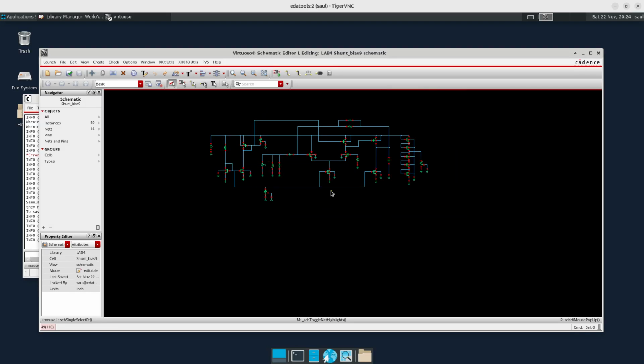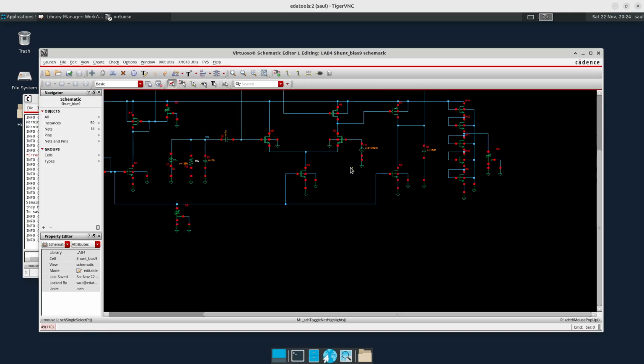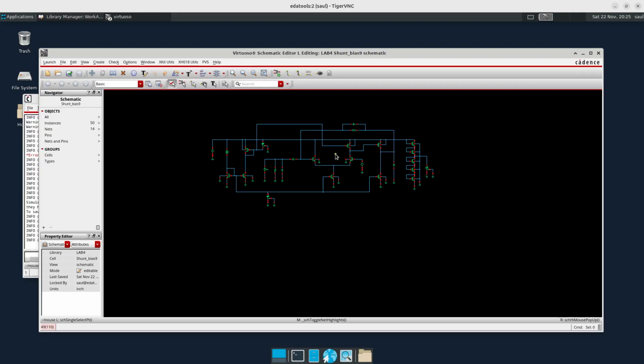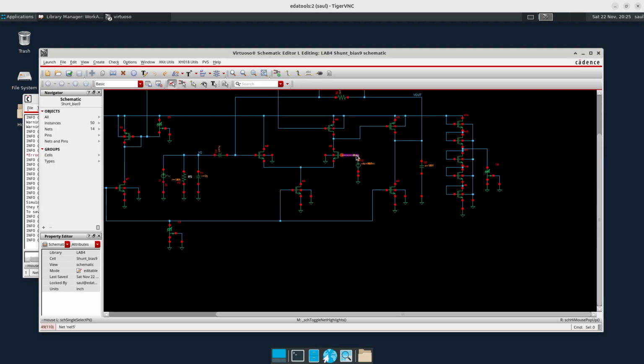Regarding the voltage reference that I needed, typically in a chip there are several voltage references available that are derived from a bandgap reference, which is a very stable voltage reference that keeps a relatively constant value over process and temperature variations and power supply variations. So there are voltages normally that are derived from the bandgap voltage references. So we can tap into one of these for the reference that we need, around 900 millivolts.